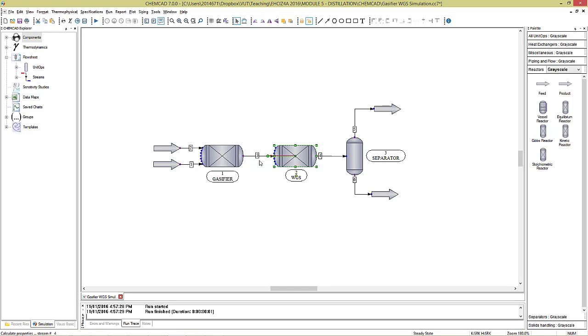If the pressure needs to increase, I need to see a compressor. If the pressure needs to reduce, I need to see an expander, a valve. If you're feeding steam, I need to see where the steam comes from. Usually you are given water, steam is not available on site. I need to see you boiling the water to form steam that you're going to feed into your system.